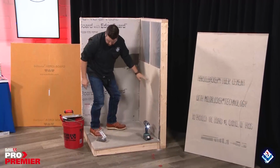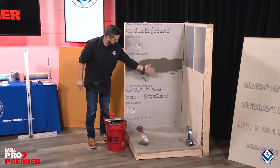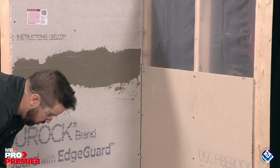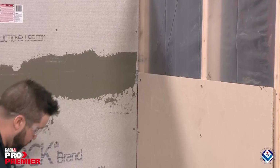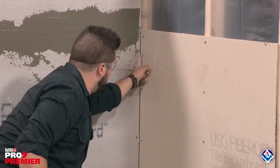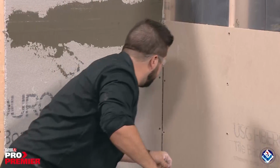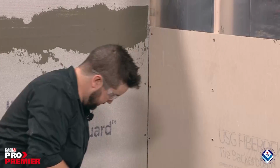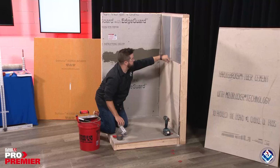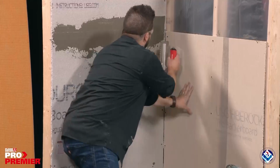All right. So if you were to look into that corner, you'll notice that cavity in that corner right there, there's a gap in there. So when we go to tape that joint right there, we don't want to fill that gap with any kind of mortar. We want to leave that clean. So it takes a little bit of extra care and caution when doing a corner like this. But let's get this ready to go, and I'll put that right there. And then let's tape this corner together.